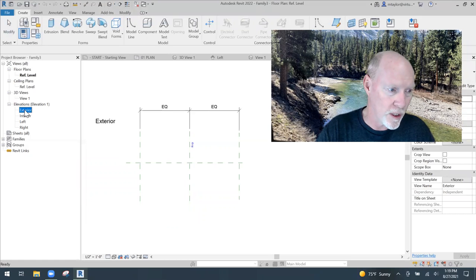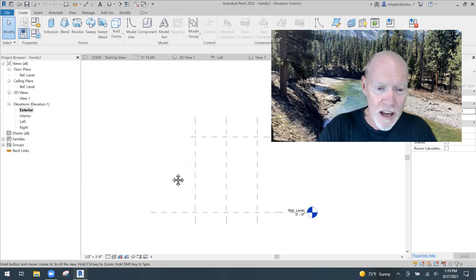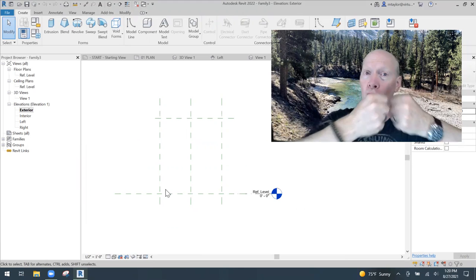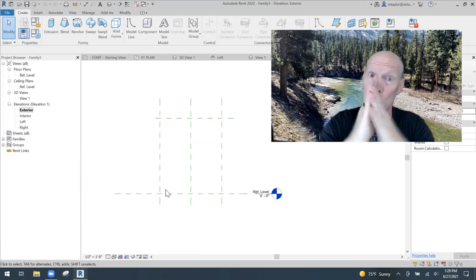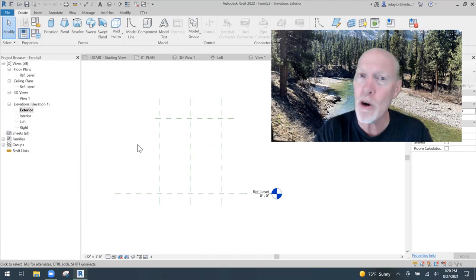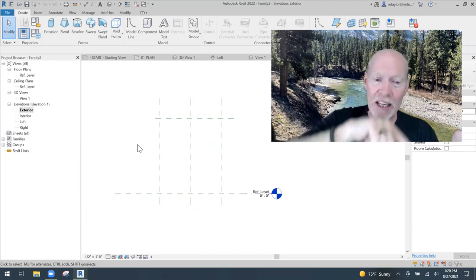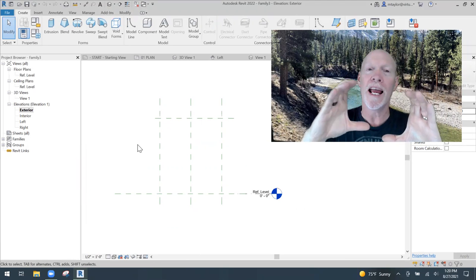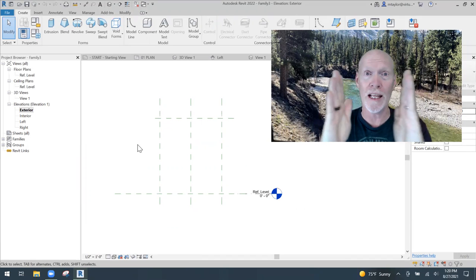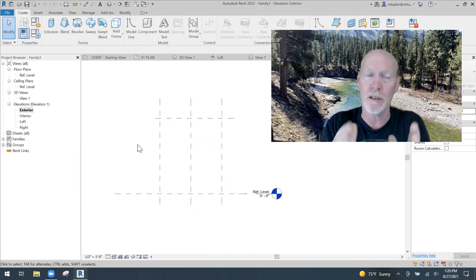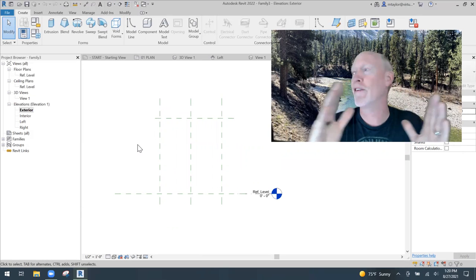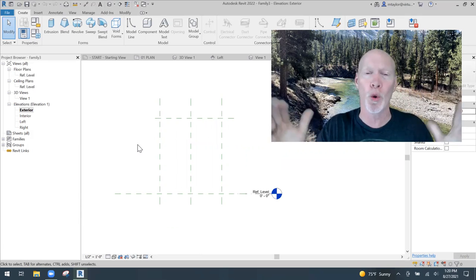The only thing they've done for us is they've put in the sides, and if I go to the exterior view of this thing, so you can see it, they have put the top, bottom, and the sides. Whatever we build automatically extends and stretches to fill this box right here. That's how curtain walls work. So if in Revit we make the grid lines only a foot apart, my door will be a foot. If I make the grid lines 3 foot apart, it'll be a 3-foot door. And if I make it 6 foot, we're going to have a 6-foot door.